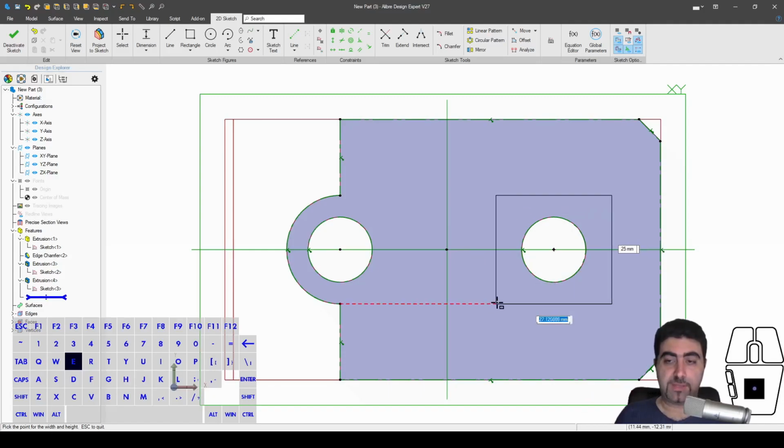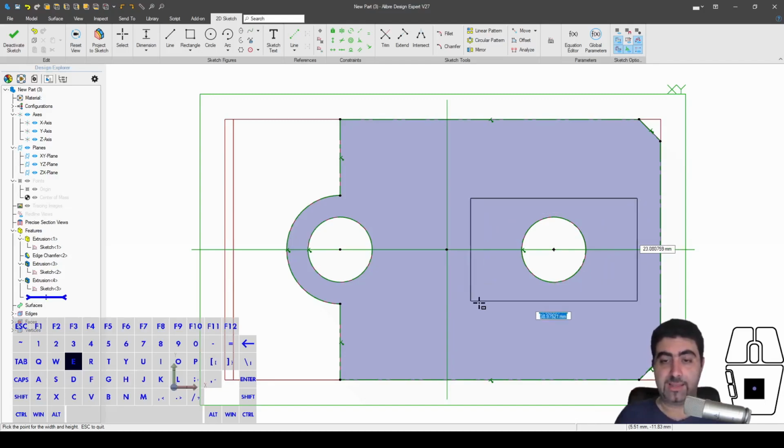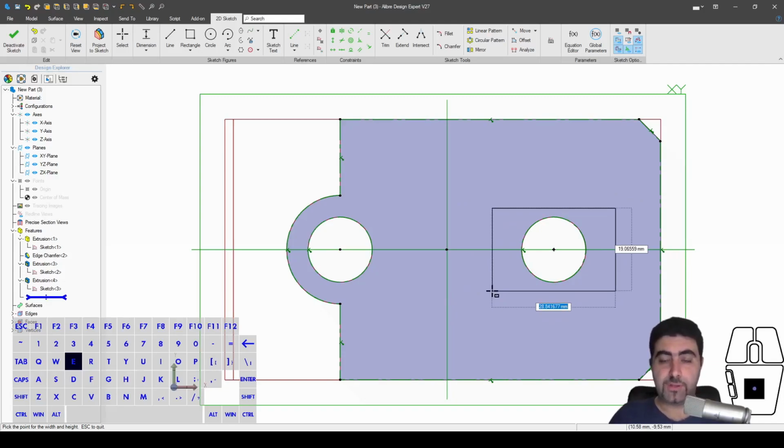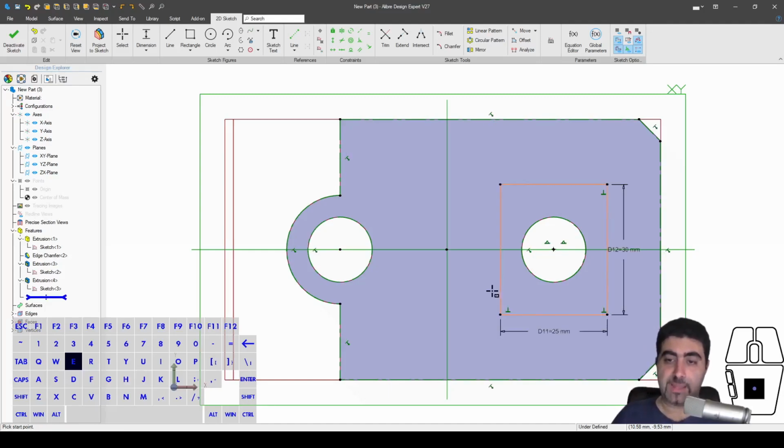Look what I'm getting. I'm getting text boxes that update with the lengths of the sides of that rectangle, right? And the first one looks like it's highlighted blue. So look what happens if I type in a value. We can type in values there. If I hit tab, that one turns green. And then let me type in a value on the other one. Now I can either hit tab or enter, and look what I got. It is creating the dimensions automatically.